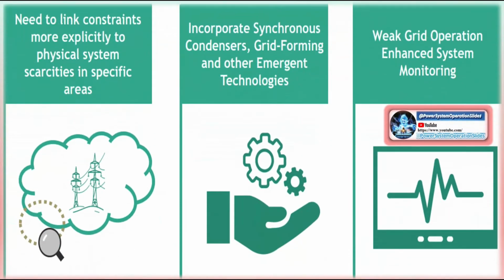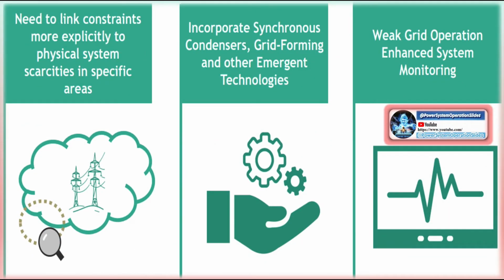Below are several reasons why the SCR is crucial. A higher SCR indicates a more robust system that can withstand higher fault currents. This means that the system has a strong short circuit power capability, and fault conditions will not destabilize the system. On the other hand, a low SCR indicates that the system may be more prone to instability and could lead to cascading failures if the fault is not cleared quickly.